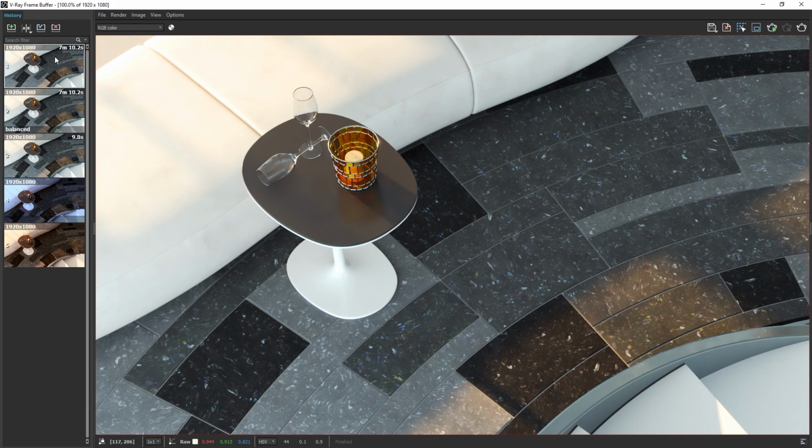You'll see as I hover over the images that I'm given some information about them as well, such as their resolution and render times. And if I right-click on an image here, I can add a note to the saved render, as well as choose from options such as loading in post-processing layers from a saved image. Also, note that at the bottom of the VFB, the toolbar gives us pixel value and coordinate information based on where our mouse is hovering over the image.